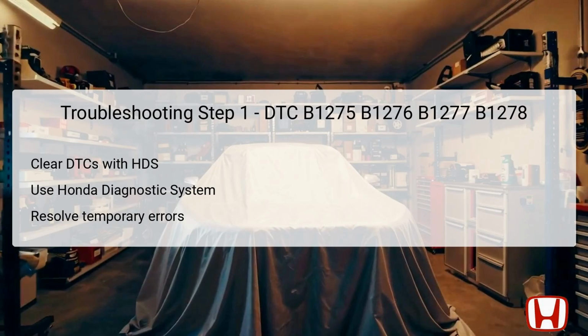Clearing the DTCs is necessary to ensure no additional codes interfere with the subsequent diagnostic procedures. Upon clearing the codes, it's important to recheck them after completing the later steps to confirm whether the issues reoccur or if they were simply intermittent errors. This step is foundational as it establishes a clean slate for diagnostics, preventing any false readings from previous issues.